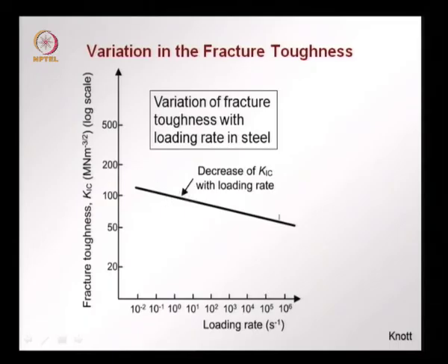This is the reason that we intuitively always try to break things very fast when we want them to crack. We apply a very fast load when we want something to crack into two, where we are intuitively decreasing the fracture toughness by increasing the loading rate. So, we will stop here with this part.